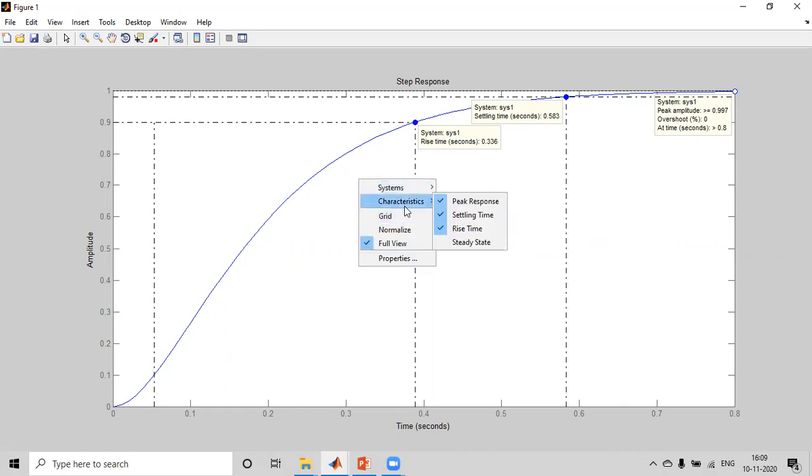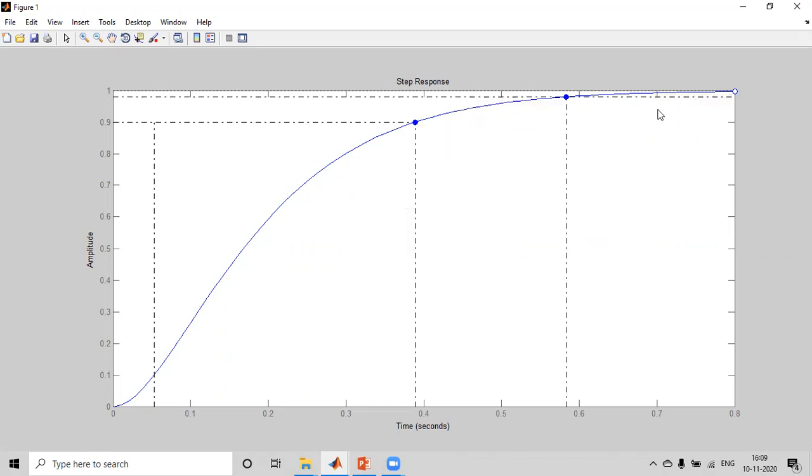And coming to the next parameter, steady state. We need to observe the steady state. For observing the steady state, here also the final value will be 1, so here also the steady state error will be 0. So we are getting a final value of 1. This is the second program output. It is a critically damped system. We are not having any oscillations. Overshoot will be 0.